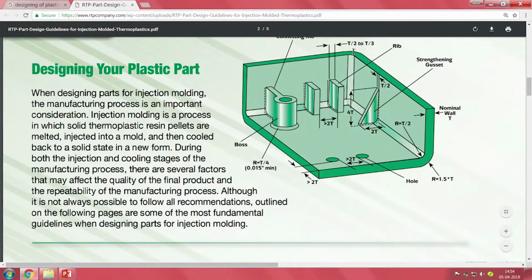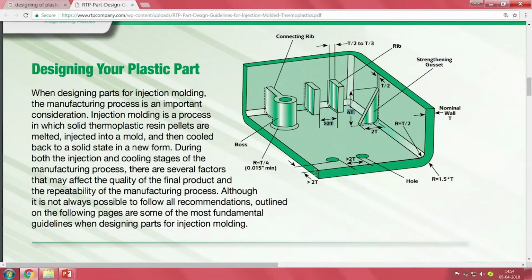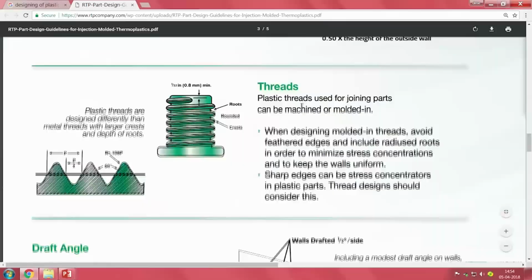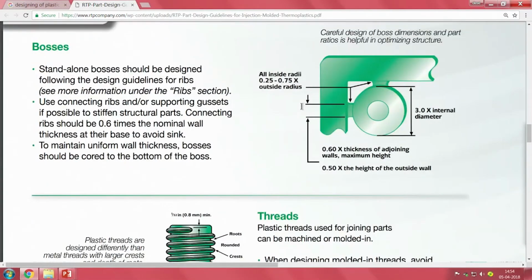Imagine material is being injected in this corner and material has a tendency to flow here, and here, and it will come and join in this place and may end up with what is called a cold shut. So, by the time they come here, if you make it too warm or too hot, there are some problems. If you make it cold, you may end up with two surfaces joining together with a joining line which is visible, which is a little possibility of a problem. So, if you go to the internet, tremendous amount of data is available here.